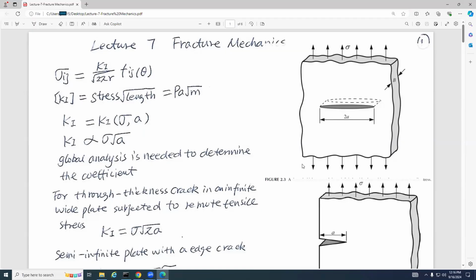Okay, guys? As I always say, for us mechanical engineers or aerospace engineers, the units play a very, very important role. Whenever you do something, you cannot just give people a quantity without a unit, unless it is dimensionless, just a ratio. You guys agree? We need to keep this in mind. The stress intensity factor's standard international unit is Pascal square root meter, and we also have the US customary unit.